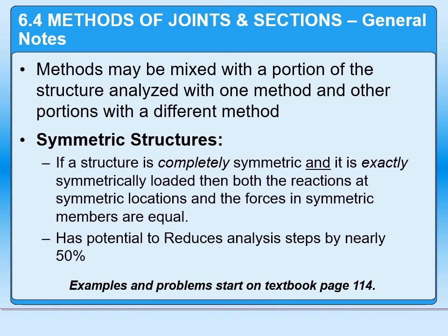Another efficiency to keep in mind is taking advantage of symmetry. As we said earlier, a lot of trusses are somewhat repetitive, and in fact, many of them are very symmetric. Most roof trusses and bridge trusses are symmetric in that they are supporting the same load on either side, so they're built the same way on either side. Now, it's important that they be absolutely symmetric or completely symmetric. Even if one member is off, they are no longer symmetric and you can't take advantage of it.